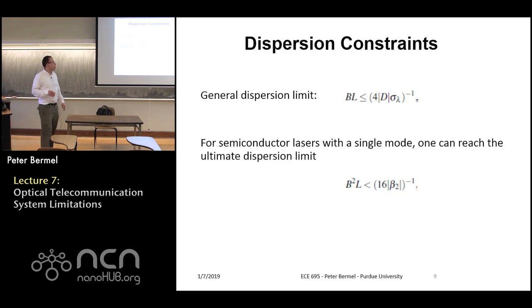And then for the dispersion, going back to that, what this is trying to get at is this fundamental limit, which we talked about in the first week, which was just that the bit rate times the time delay has to be less than 1. Otherwise, your first signal starts overlapping with the second signal, with the third signal, and then you can't tell what information is what anymore.